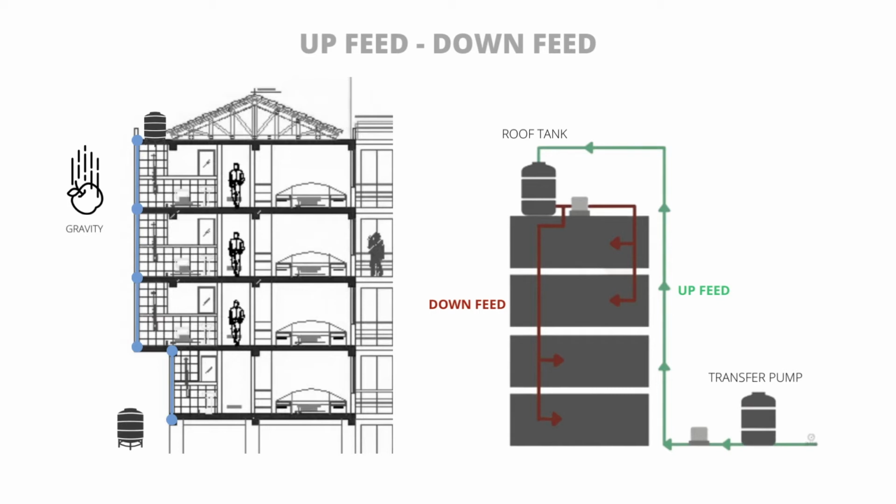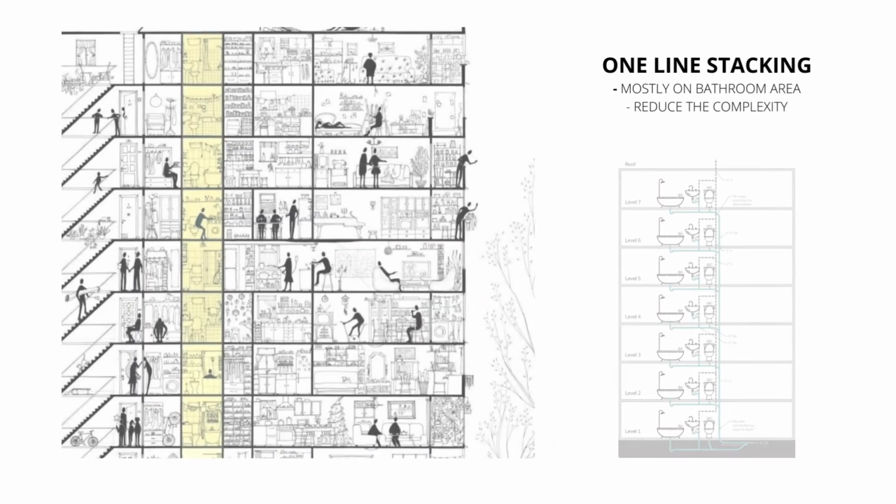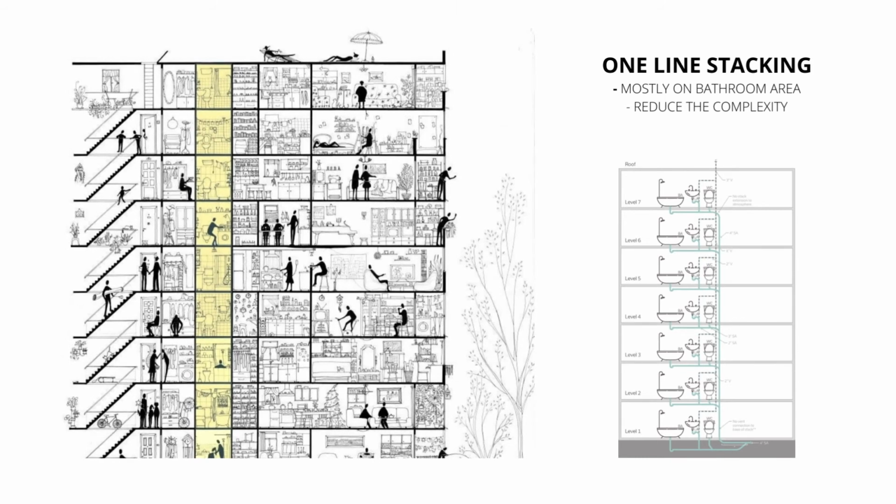The water system is most likely to be installed alongside any area that requires the usage of water, for example, the kitchen, laundry, or toilet. The pipe must run along the toilet area, regardless of where the toilet is placed. Most multi-story buildings, however, are likely to stack the toilets in one line, which could reduce the complexity and the time of installation and labor, while also reducing materials and bringing sustainability to the design.